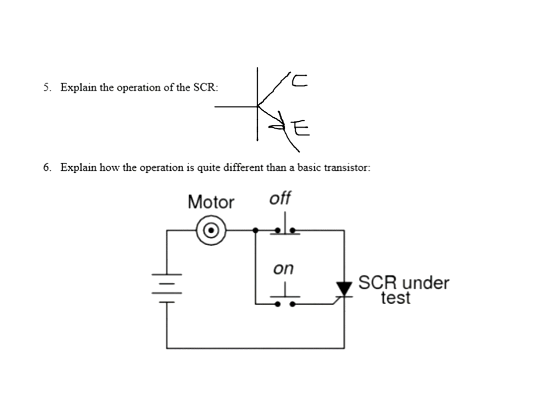So I have a lot of current flowing in there, the collector and the emitter. Now, if I have 0 volts on the base, between the collector and the emitter, it looks like an open switch. If I put 0.7 volts on the base, current flows and it looks like a closed switch between the collector and the emitter. That's how it works.